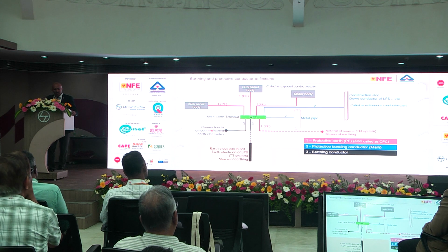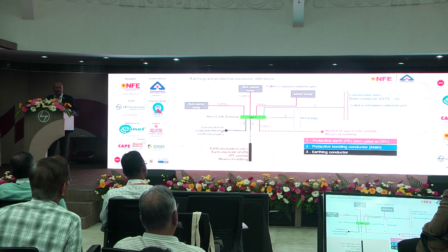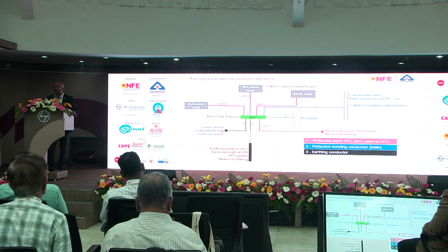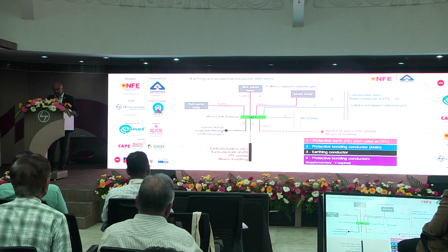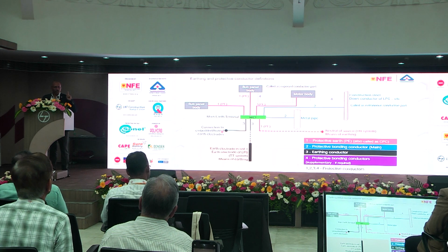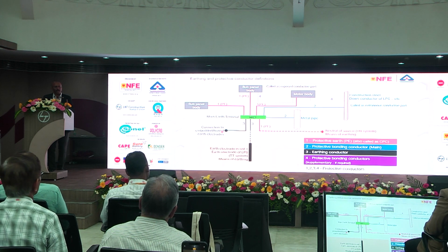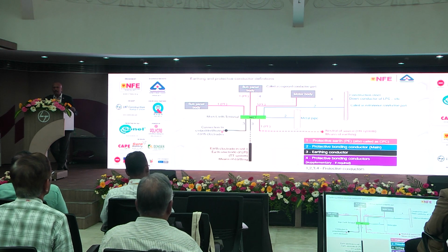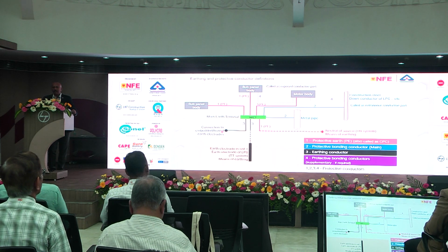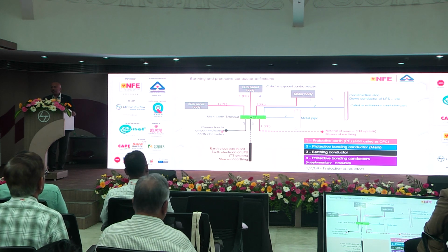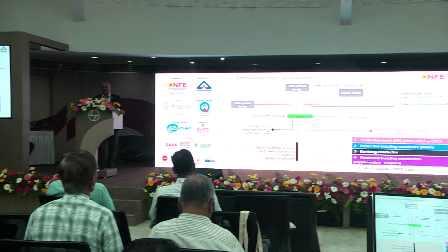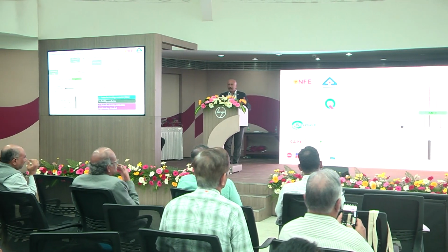Then this MET is also connected to other buried metal parts, for example, a lightning protection system, or some buried pipeline and so on. This is called protective equipotential bonding, which is the first and the most important safety measure against electric shock and electric arcing. This kind of picture was never included in the IS standards, but the CPWD manual, Annexure F, has included this picture, not only now, a few decades back. This picture originated from one of the 1965 standards. CPWD kept this picture and they only put this color.